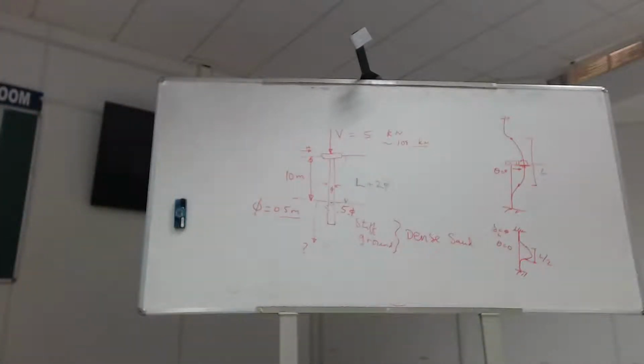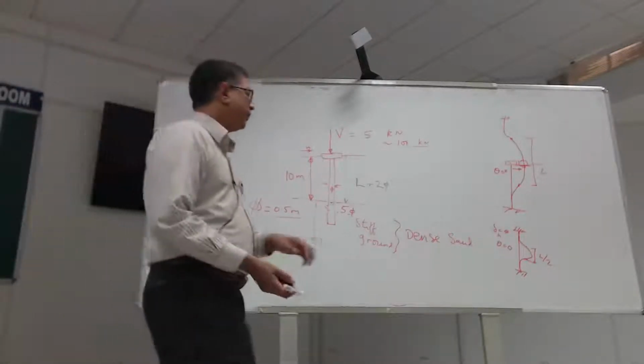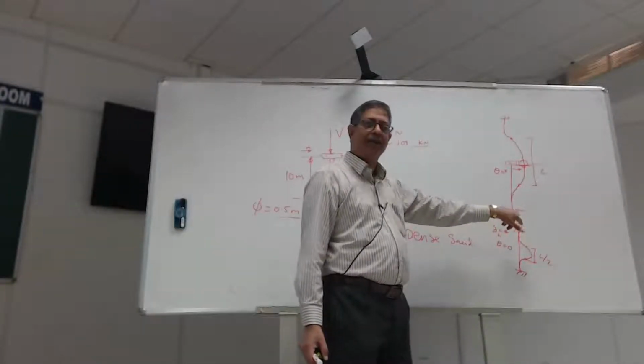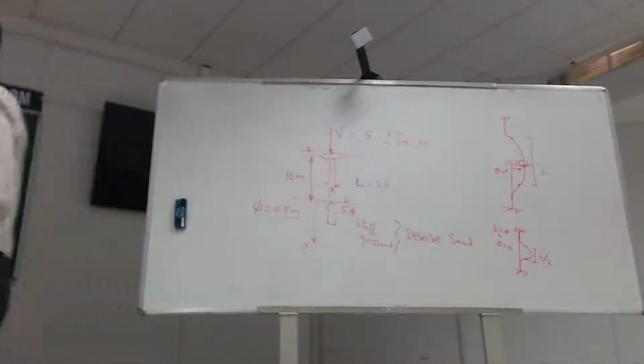Try to draw the deflected shape you get, and measure the distance between points of contraflexure. That should give you your effective length quite easily. Beta is an easy way to formalize that, but this can be done for all kinds of combinations. For example, if I allow this to partially rotate, then if I can draw the shape, I can get the beta value for it.